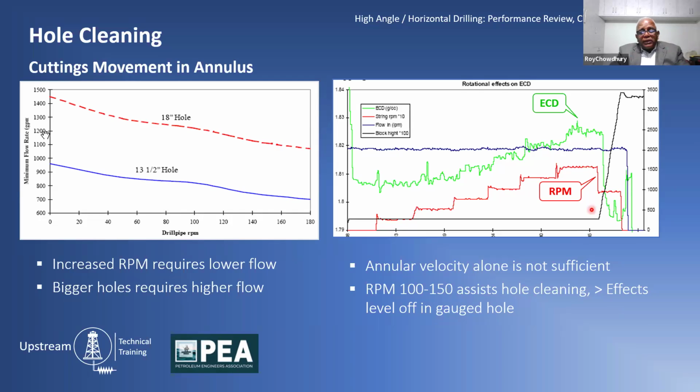And this is where you have to stop and say, do I really want to spend more energy? Because more RPM means you could be causing casing wear. That is possible, because these horizontal wells take a long time to drill. Your bottom hole assembly could be in the hole for a longer period of time. So obviously you could be running a casing wear model too, giving thought to how far I can drill without causing much damage to my pre-existing casing.